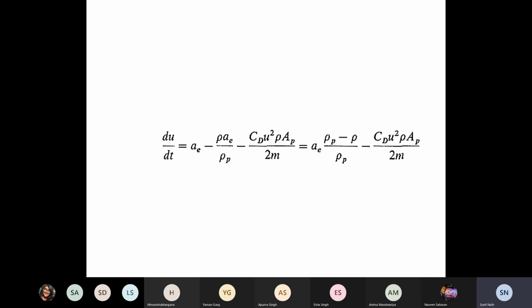The small m that you have, the mass, please write that in terms of the diameter dp of the sphere. Find out the projected area of that sphere, and then obtain a general equation which is valid for any flow regime, but now only for a sphere.